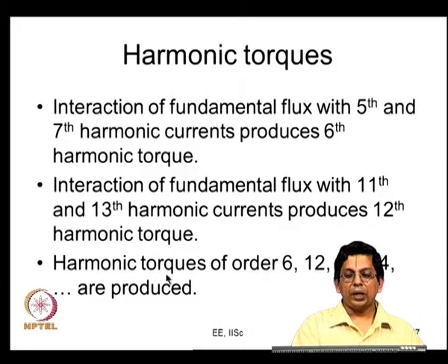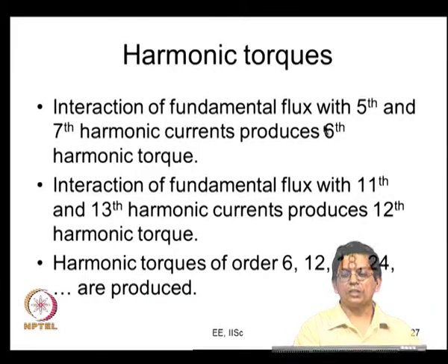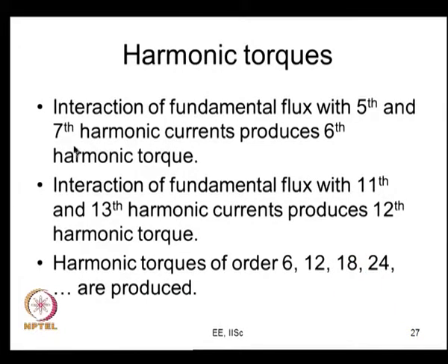So you can see that you have the fundamental flux and it interacts with the fifth and seventh harmonic. The fundamental interacting with the fifth harmonic current would, for example, produce a sixth harmonic torque, and the fundamental interacting with the seventh harmonic would also produce the sixth harmonic torque. Again, the fundamental flux would interact with the 11th and 13th. So the relative frequency is still 12, that is the interesting point.